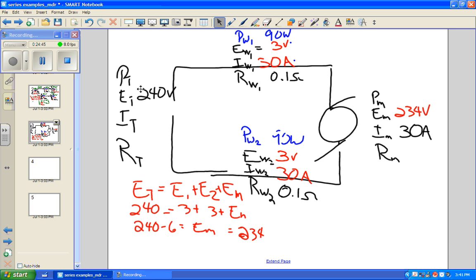What does voltage drop do? Does it do anything? Nothing constructive, but what it does do is it heats these wires. It heats the wires. That's what voltage drop does. It's heating the wire. Now, do you want to pay for a lot of wire heating? As little as possible, right? And the things that can, well, we'll talk about that next semester and how we can control voltage drop and things like that. Whole different ballgame. All right. I think that's